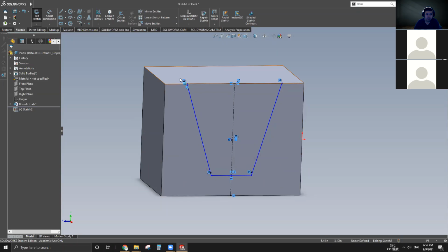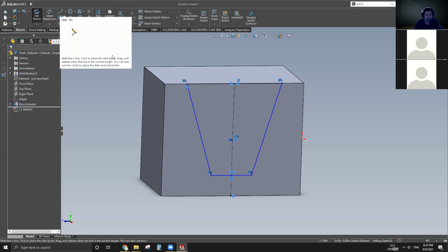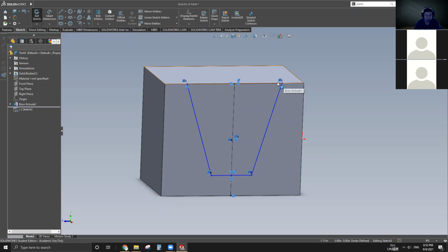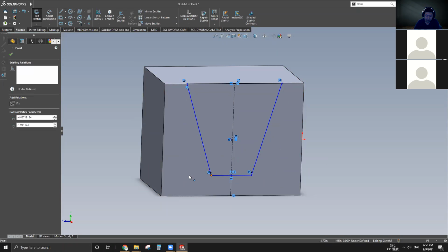It is not like when you draw some arbitrary lines, from here to there and close it, and when you move this point, the right side would be messed up. So this is why I use mirror. And when you're going to build something symmetrical, I strongly recommend you use mirror because of all those relations.